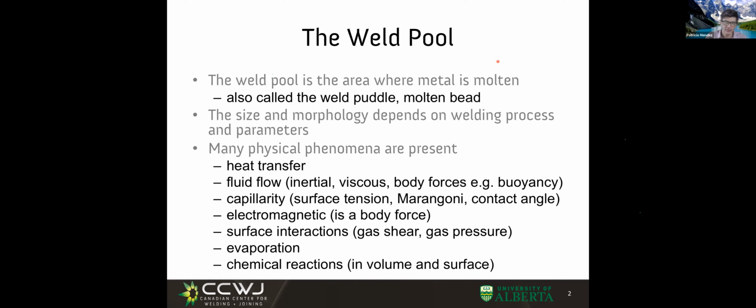Whether we heat fast or slow, or cool fast or slow, the edge of the weld pool is pretty much the melting temperature. Other temperatures, for example solid state transformations, are quite affected by heating and cooling rates. But melting has relatively little effect for the typical velocities present in welding.